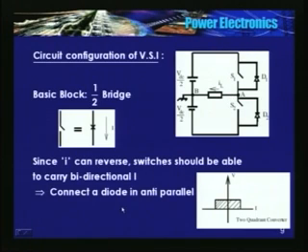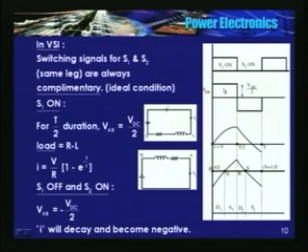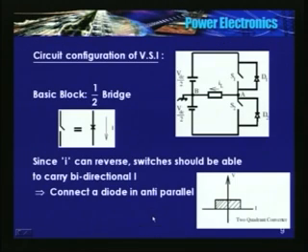But then we found that positive voltage is applied to the load, but from P to Q current is negative. So in this circuit, current is flowing from B to A, and this point is connected to this point. So it can happen only when D1 is conducting.